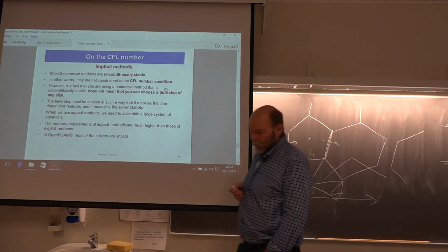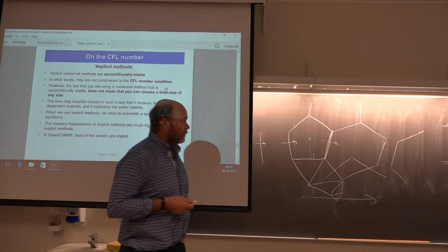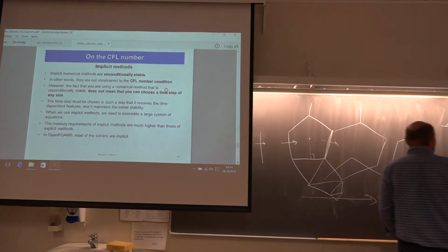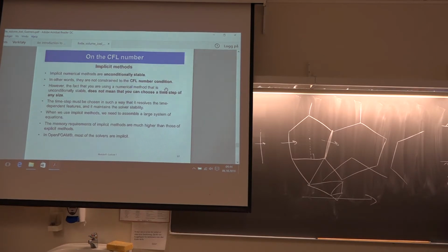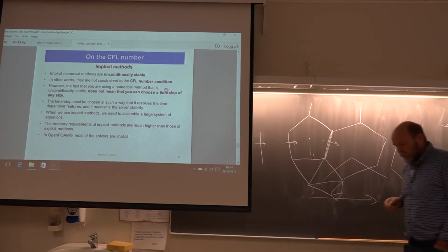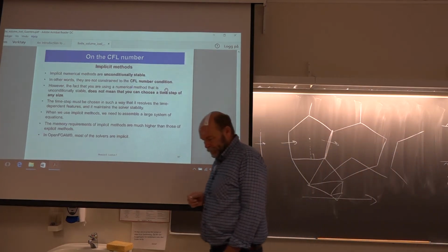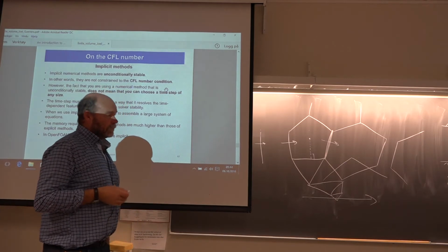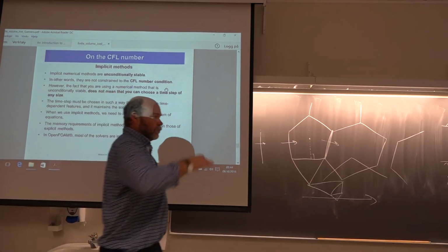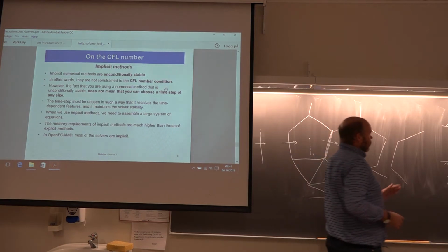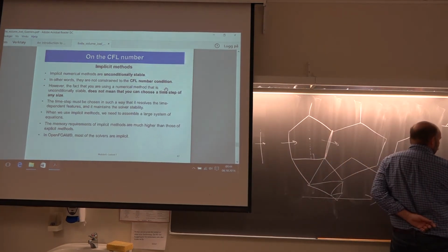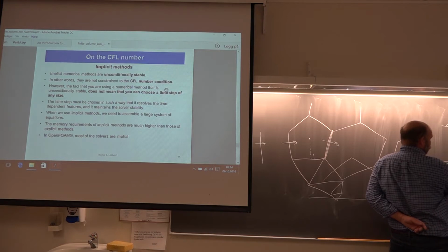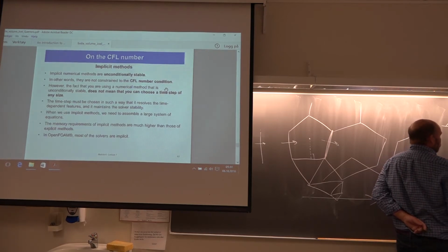But in the startup process, the equation describing this problem will be time derivative equal viscosity times the double derivative with respect to, say, y in this case here. And you start initially with the velocity equal to 0, and at time equals 0 you start the top wall, and then the solution should tend towards the steady state as time goes by.